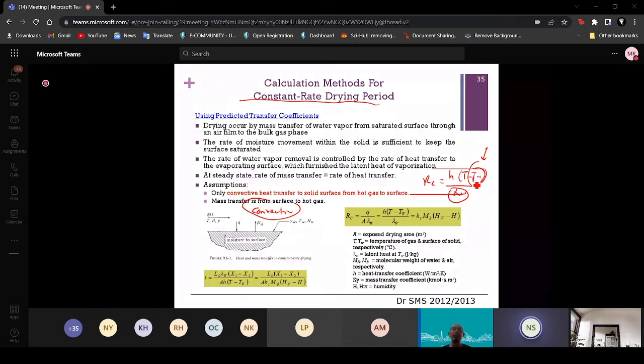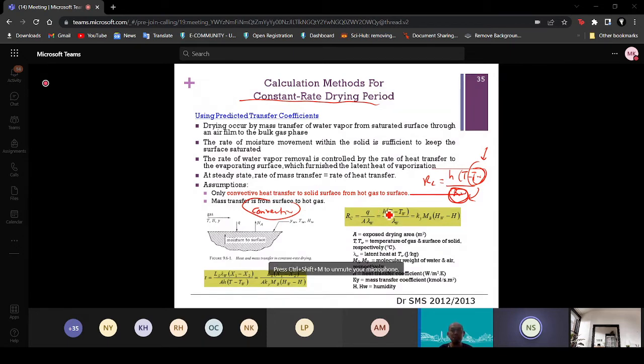Let's say you determine T wet bulb is about 40 degrees Celsius, and then you can go to your steam table to find the latent heat at 40 degrees Celsius. Okay, it has to correspond here. That's why I say it is very important. The others are okay. The heat transfer coefficient, like this one, is just expanded. Expanding, you have LSA, X1 minus X2.